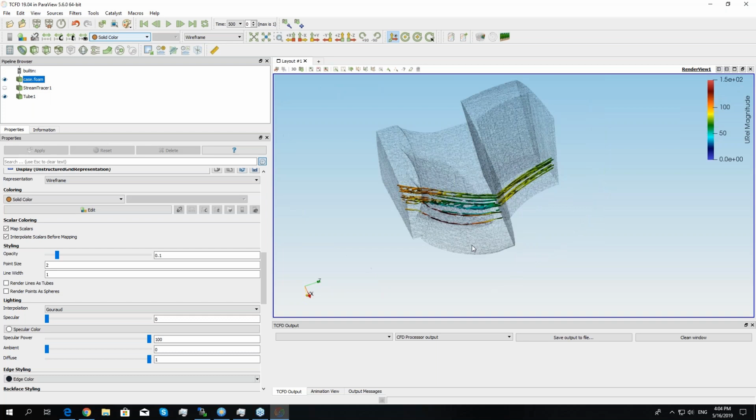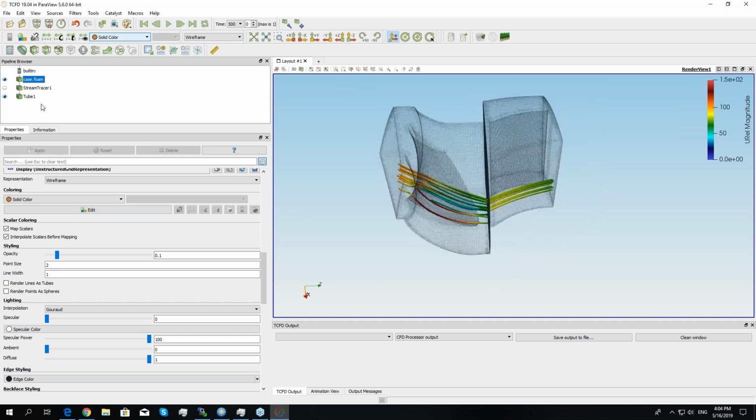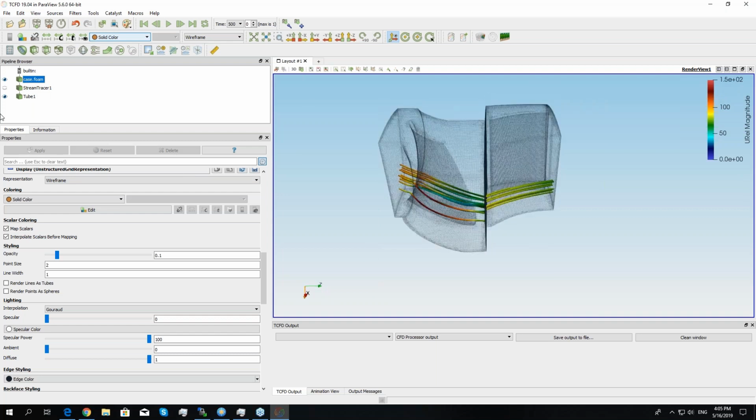Okay. So the last thing on this example, I would like to show you how to, for example, generate average value, surface average, or mass flow rate average value on any slice you prefer. So let me make a slice. So I will make a slice through my domain.